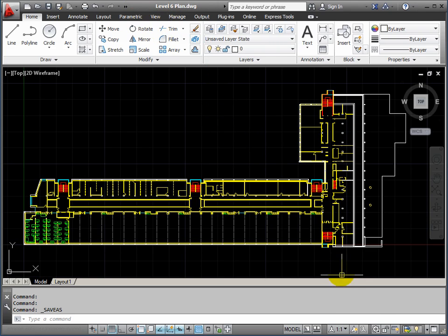Okay, now if you can't see it up there, look for the cog icon on screen, and we've got it here down at the bottom as well. We've got workspace switching. We could activate it there. Okay, the black background area is model space. This is where you do all your design work. It's a one-to-one environment, so one unit here is basically set to 1 millimeter.